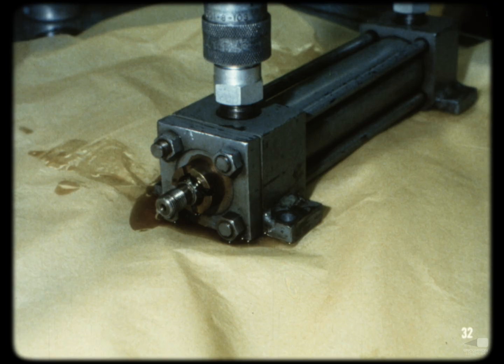Hydraulic drive systems can present leakage problems. Oil leaks are usually progressive, but easy to spot, and can be repaired conveniently with little machine downtime. Also, hydraulic drive systems must periodically have the fluid and filters changed and require a warm-up period before operation.